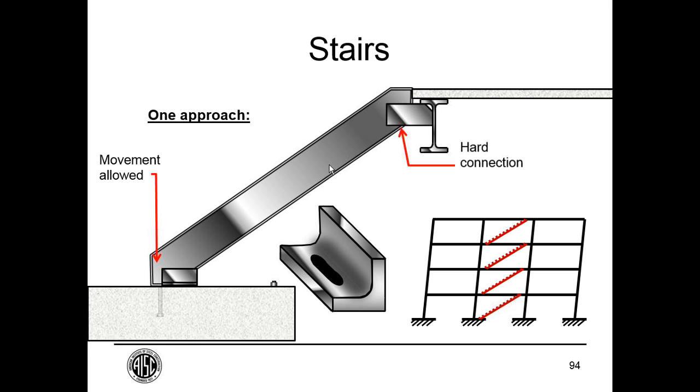In some buildings, in retrofit, where there are a number of things that have very little displacement capacity, the best approach is to stiffen the entire system so that the displacement demands on those elements aren't that great. So for retrofit purposes, it's often very difficult to catalog and address all of the things that need extra displacement capacity and fix those, as compared to reducing the displacement demand by adding very stiff elements.